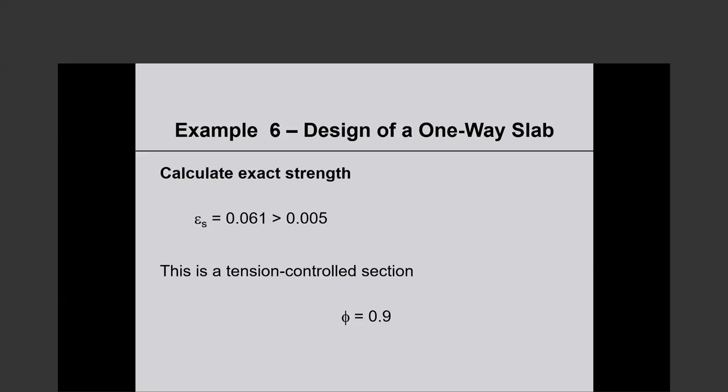So in section 6.3.2.4.1 of BNBC 2020, there is a coefficient for flat plate slab, and that coefficient is 0.25 Ig. What should be this coefficient for beam slab? It's very specific.